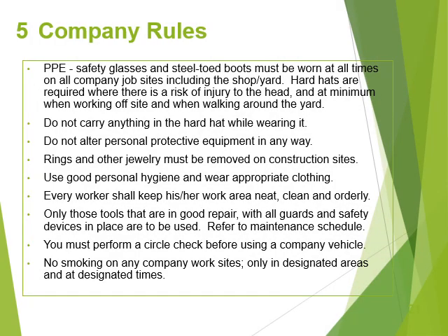PPE, safety glasses, and steel-toe boots must be worn at all times on all company job sites, including the shop and yard. Hard hats are required where there is a risk of injury to the head, and at a minimum when working off-site and when walking around the yard. Do not carry the hard hat while wearing it. Do not alter personal protective equipment in any way. Rings and other jewelry must be removed on construction sites. Use good personal hygiene and wear appropriate clothing.